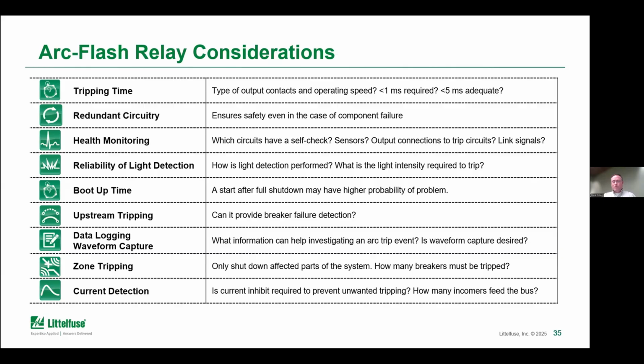But when you're coming back online after maintenance, that could be a time when you have a higher probability of an arc. And so when the equipment is being energized from a dead start, what is the boot up time on the protection devices? How long is it going to be that they can detect this arc, after this energizing time? So that's something to be aware of.